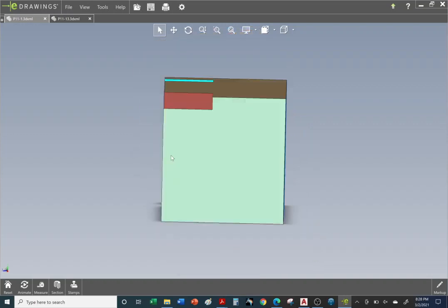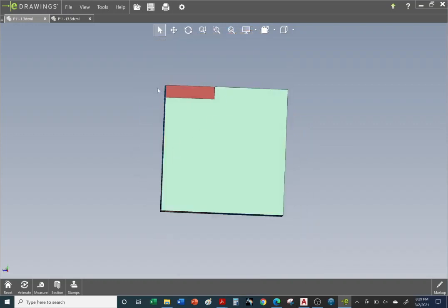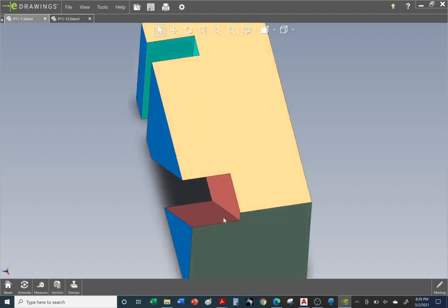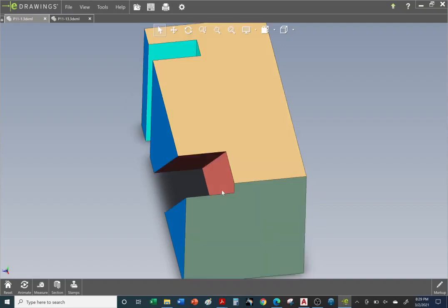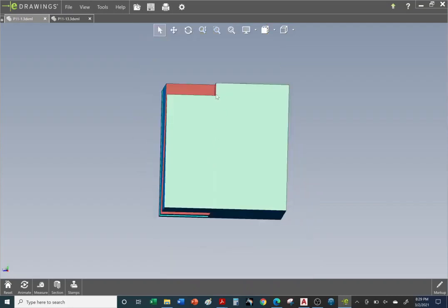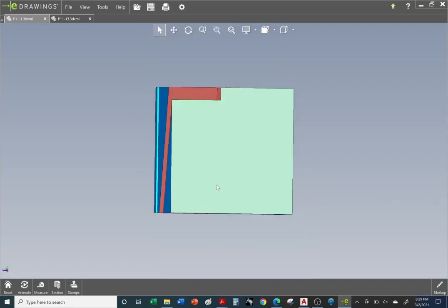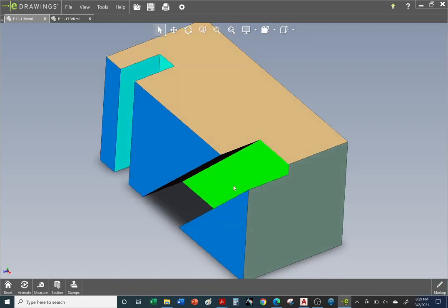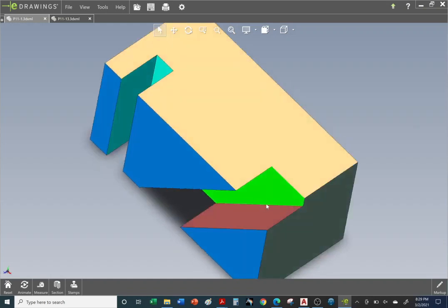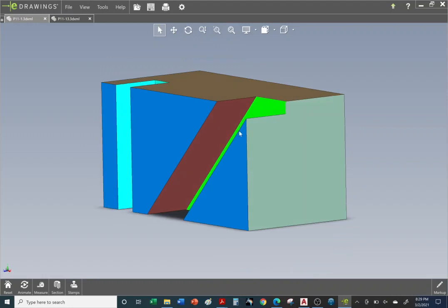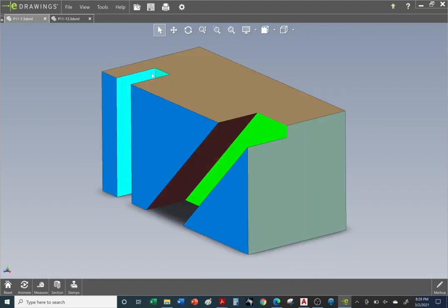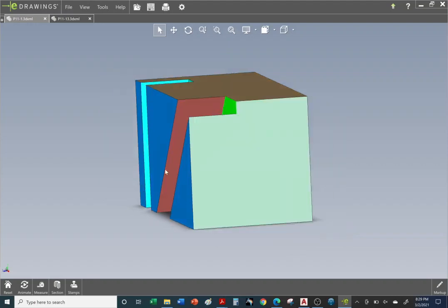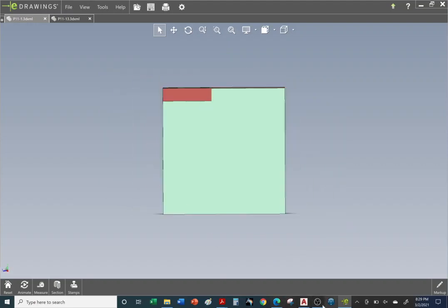All right, so we can see this portion of the salmon colored opening here. We can see part of it, but we cannot see it slide down. So we need to draw a red hidden line going straight down. That red hidden line is going to take care of this surface, this edge, this inside edge, and also it'll take care of the depth of the cyan vertical groove. Okay, so let's go back to AutoCAD.